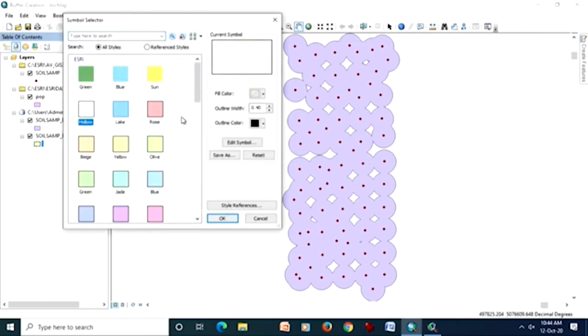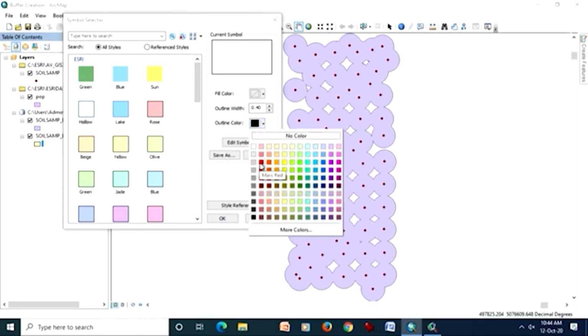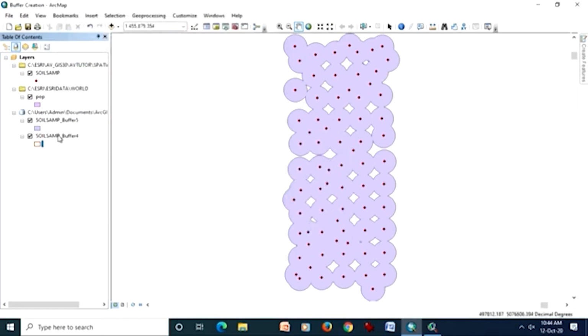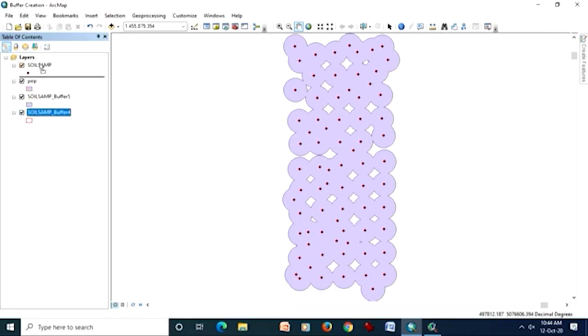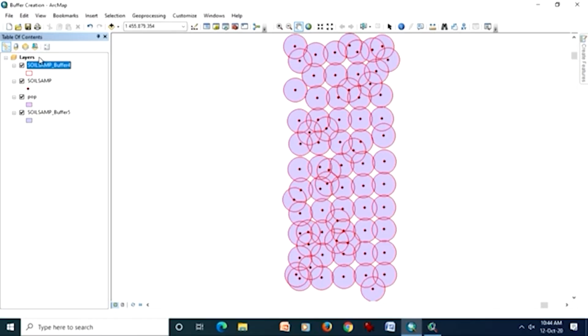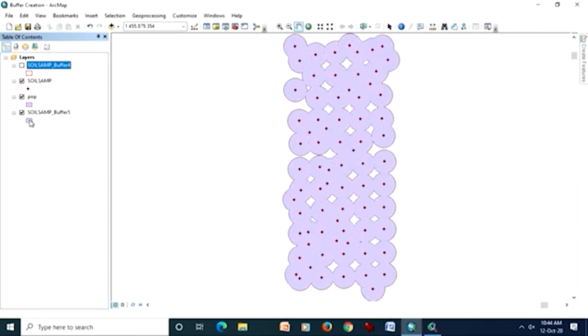And what I am going to do is overlay the previously created buffers on top of this, so you can see what I am talking about. See, these red circles are showing those overlapping buffers, but the new buffer which has been created is without any overlap, and all has dissolved. So it looks more realistic and more useful than without dissolving. So this care must be taken.